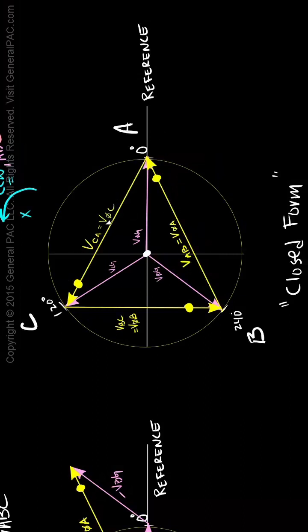It's connected to the non-polarity side of V phase C. The polarity side of V phase A is connected to the non-polarity side of V phase C. Now look at what the polarity side of V phase C is connected to. That's correct, to the non-polarity side of V phase B. So the polarity side of V phase B is connected to the non-polarity side of V phase A. Here.